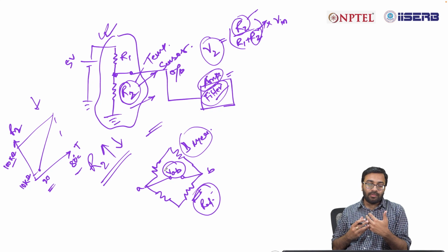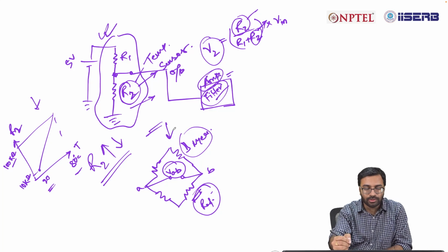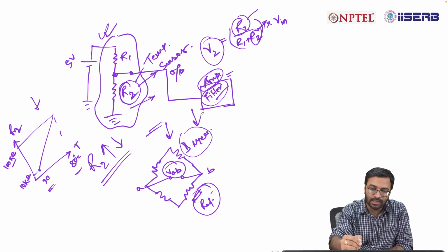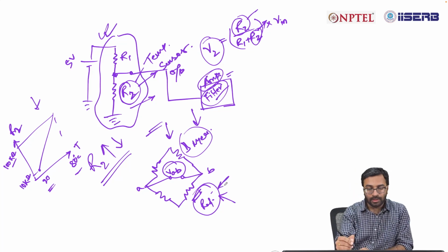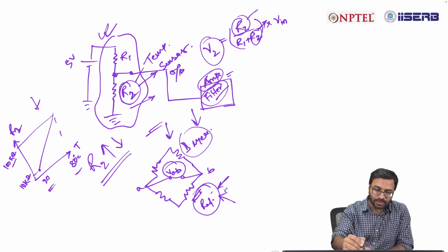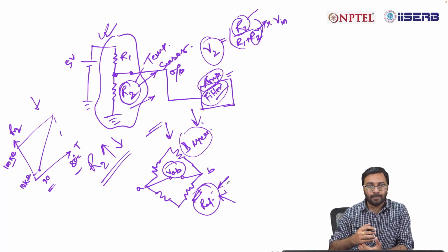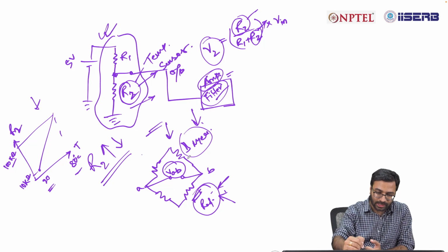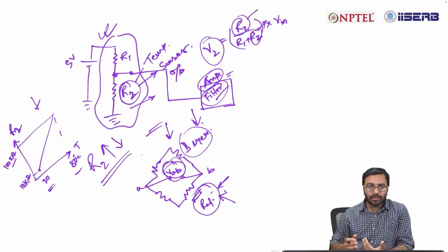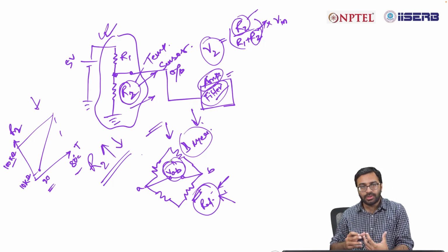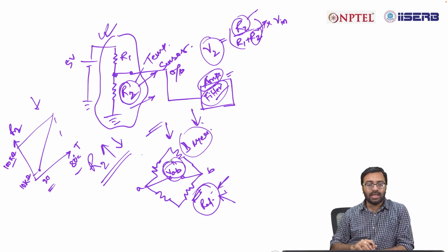And one of the very important advantages that you may get in case of a Wheatstone Bridge structure is, if there is an influence here, the same influence will be applicable for this sensor, because both are same sensors, one is a reference sensor. In that case, that influence will be cancelled out. If it is not getting cancelled out, definitely you will get a VAB potential, which will help you to modify your system accordingly. So these are the advantages you may get using those basic interfacing circuits, and that is why the interfacing circuits are very important.